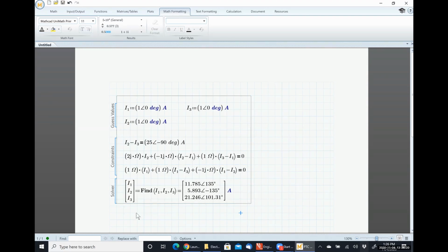Okay, so for the omega, you click on the symbol omega, does it just know that you're talking about resistance? So how I got those omegas, if I type capital W and Control G, that converts the W to its Greek counterpart, which is omega.